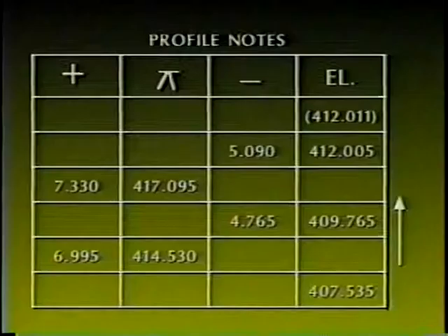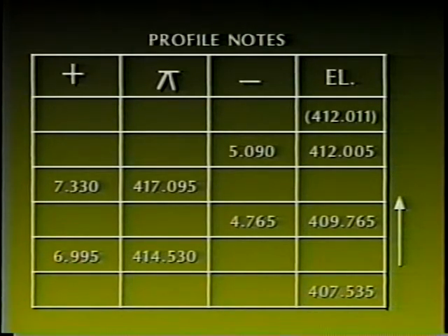The following illustration demonstrates several methods used in taking field notes. Our first example of level notes shows a differential profile level note using a Philadelphia type foot rod. Notice the notes are taken going up the page. Taking notes going up the page simplifies retracing the level run in the field.